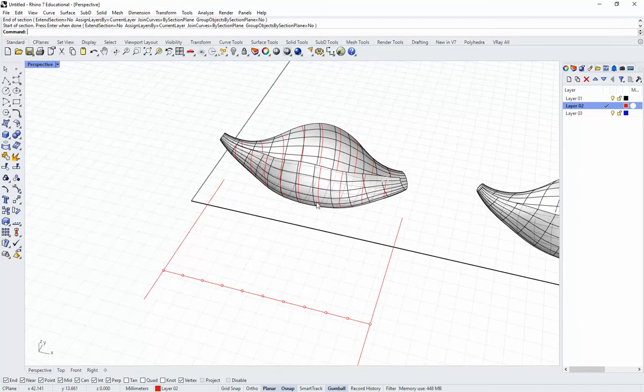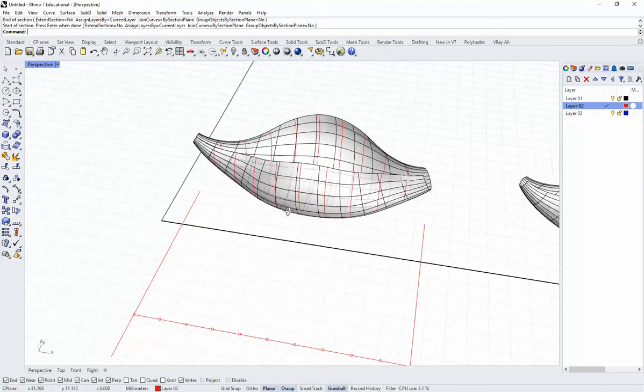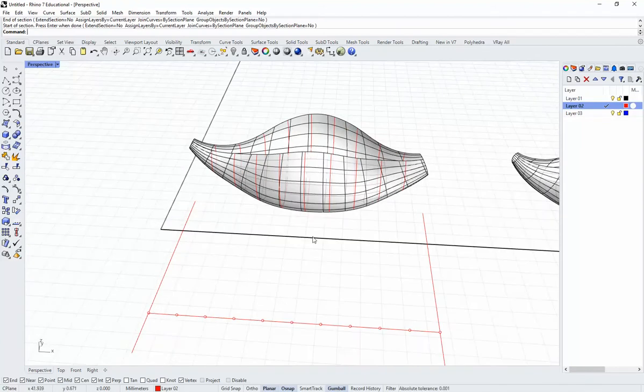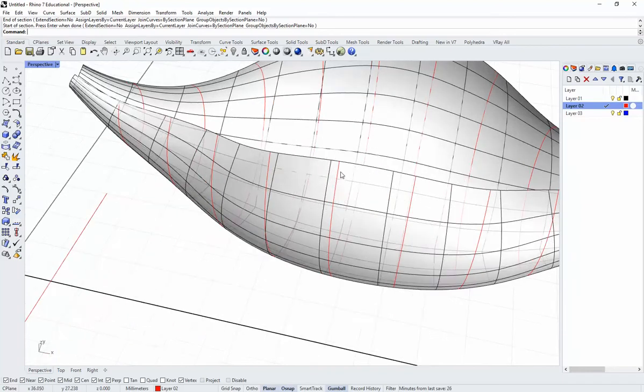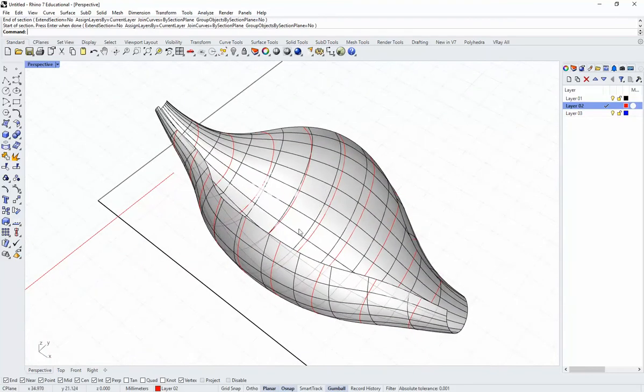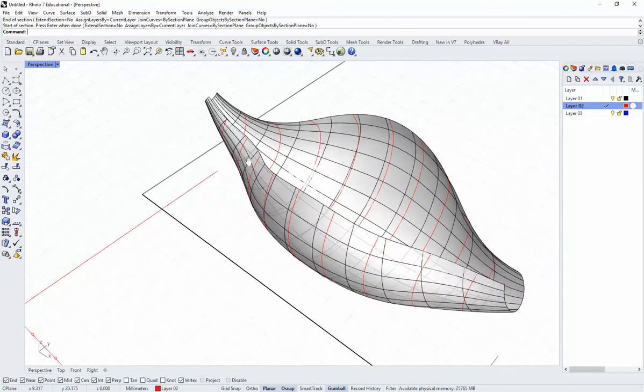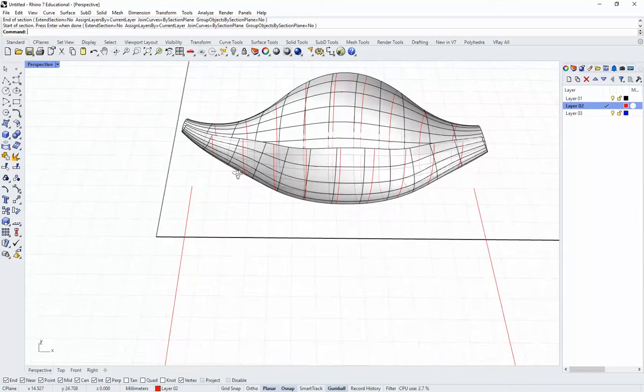But if you were imagining a certain way of adding thickness to these, you may want to change up these dimensions just a little bit, and we'll talk about that in just a second. But for the meantime, you can just imagine these are center lines, and what we'll do is extrude them out in both directions to make the thickened frame element.